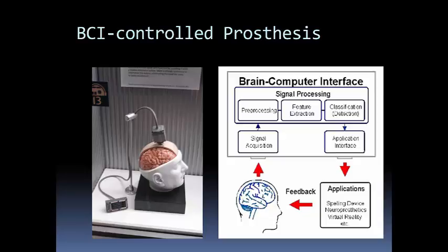To do so, the bionic arm's computer is constantly acquiring the brain activity of the user, pre-processing the signal to remove noise and artifacts, extracting features from the signal using something like, say, time window-based FFT, then classifies these features. For example, does this feature mean anything? Does it mean I should move the arm up, down, left, or right? And then the computer finally instructs the arm to move based on the results of this classification procedure.